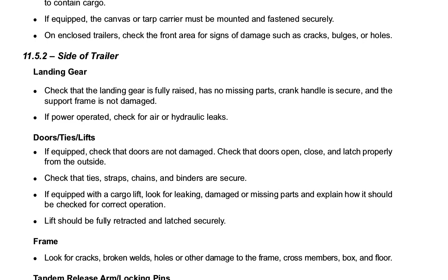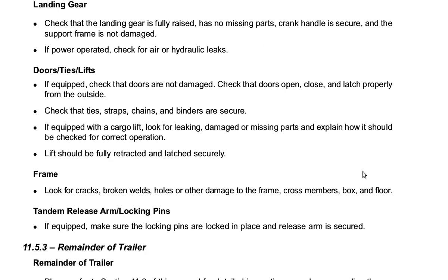Doors, ties, lifts. If equipped, check that doors are not damaged. Check that doors open, close, and latch properly from outside. Check that ties, straps, chains, and binders are secure. If equipped with a cargo lift, look for leaking, damaged, or missing parts and explain how it should be checked for correct operation. Lift should be fully retracted and latched securely.